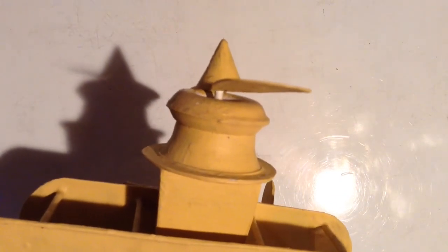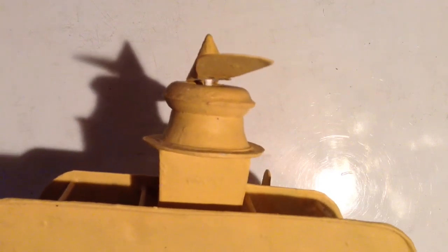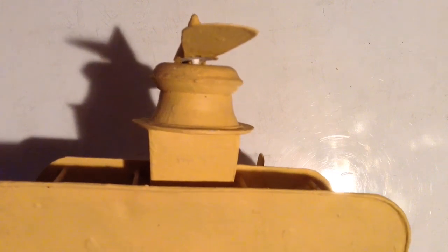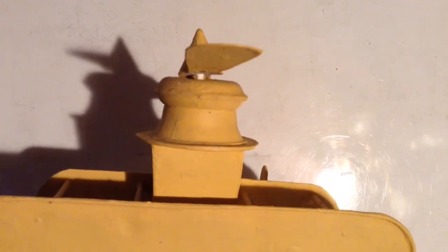Okay, because forces on a rotating body result in a change of the body's position 90 degrees or 1/4 of a circle past where the force is applied, the propeller blades will tend to go forward when they are swinging up on the left side and backward when they're swinging down on the right side.